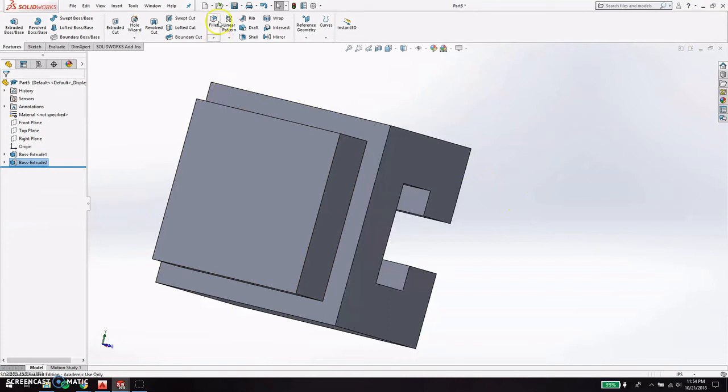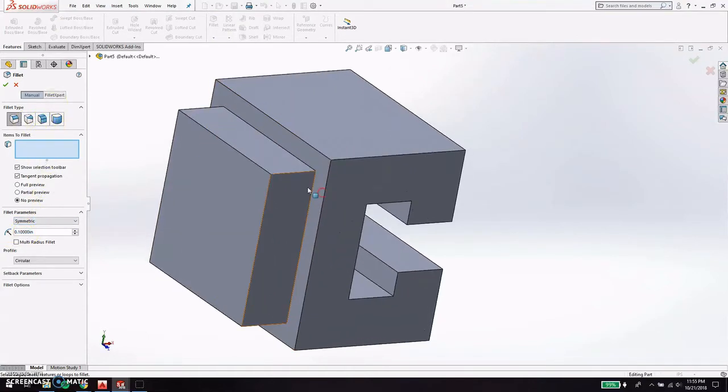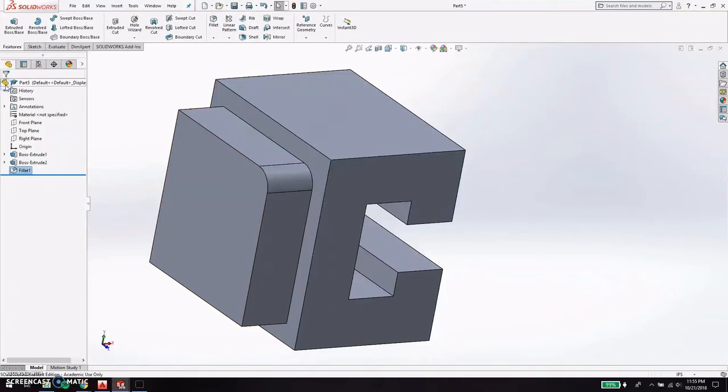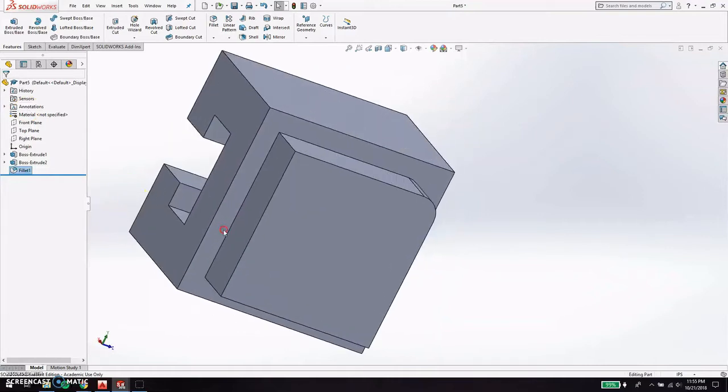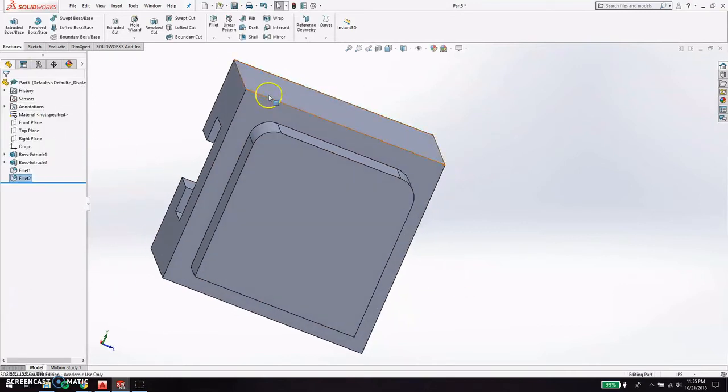If you want to make fillets on this guy, you can always click the little fillet tab, and this will show you the radius of the fillet. You can do all sorts of different dimensions here. Basically, let me figure out. Yeah, I think this is, yep, just like that. So you go to fillet, and you click this dimension right here, and then you just click the little check mark, and that'll do it. So you can fillet all sorts of stuff. Usually I don't go to that level of detail because there's not a whole lot of point in showing all of that sort of stuff.